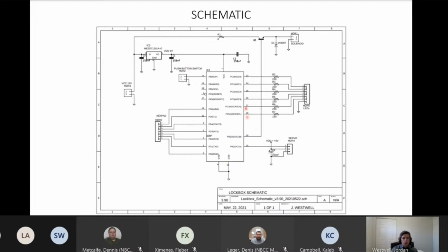And we also have up here the LED UI. We have red, green, and yellow LEDs. All of the voltage drops for the LEDs are relatively similar. So the 220 ohm resistors were chosen just for simplicity's sake, to order a bunch of these at once to drop the cost a little bit. And so there's 6 LEDs out. Physically, in the box, the LEDs have been connected on their ground side with essentially a bus that comes back to this one pin, which goes to ground.